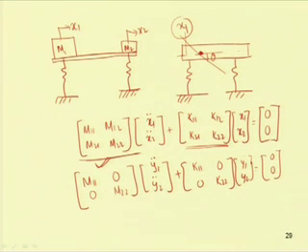So, it can be reduced to two single degree of freedom equations. In this case, the equations are coupled, but in this case the equations are uncoupled. As it is uncoupled, one can solve this equation as m y double dot plus k y equal to 0, that is that of the single degree of freedom system. So, one can get the solution easily by decoupling these equations. There are several methods to decouple the equations. One can use the modal analysis method to decouple these equations.